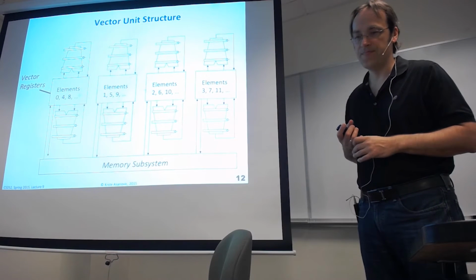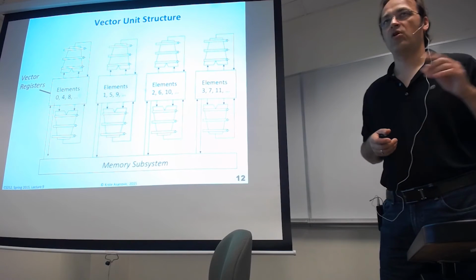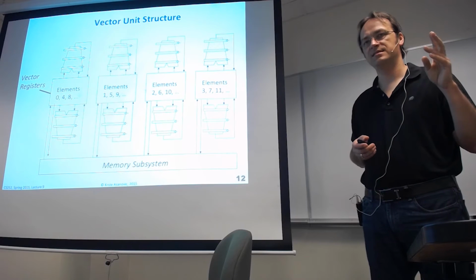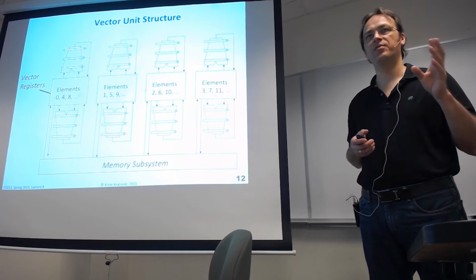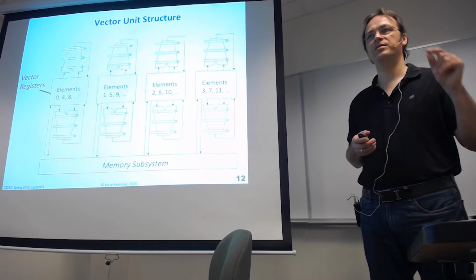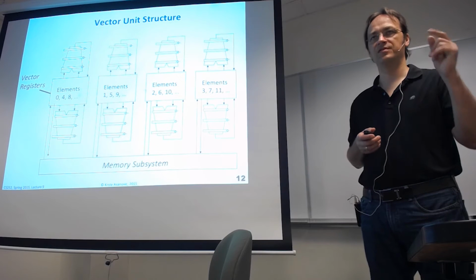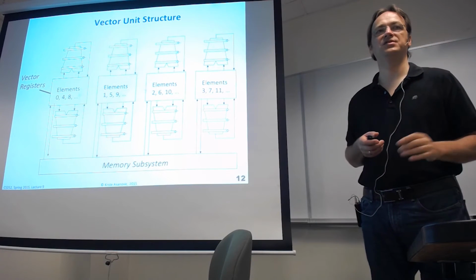So the vector units, getting back to this property: in vector instructions, each operation only accesses operands at the same element position. So if I'm doing a vector operation, element 0 in the vector will read operands from element 0 of the source vectors and write its result to element 0 of the destination vector.